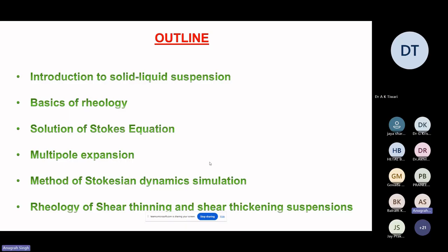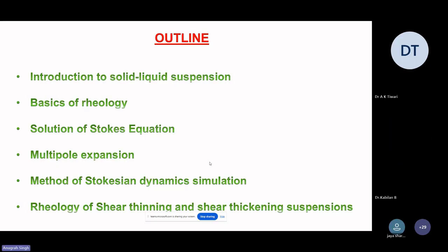And then how the solution for a single particle can be built to incorporate many-body hydrodynamic interactions through multipole expansion. And then the details of how we carry out Stokesian dynamics simulation to compute the rheology of suspension. And then some examples, where we can not only study the Newtonian one, we can also study shear thinning and shear thickening suspension.